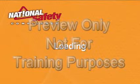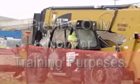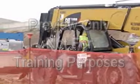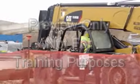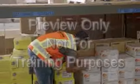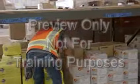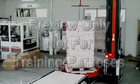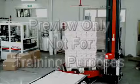Loading. Handling loads can present different hazards for different forklifts. Improper techniques or loading can cause a forklift to tip over, the load to drop, a collision, or other accidents. Prior to picking up any load, inspect it and center it as much as possible. Secure the load so it is stable and arranged safely. Loads should be secured by wrapping or banding when necessary.